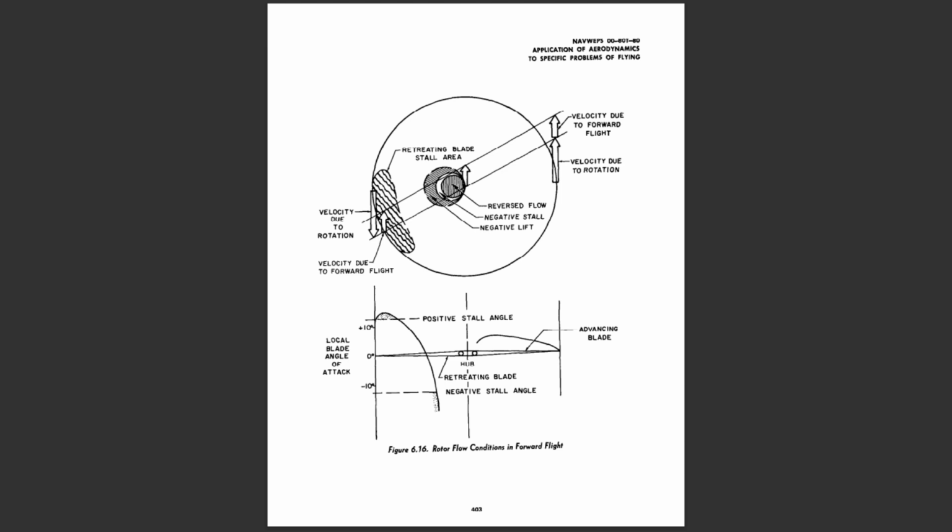If the stall is severe enough to result in pitch-up, forward cyclic to attempt to control pitch-up is ineffective, and may aggravate the stall, since forward cyclic results in an increase in blade angle of attack on the retreating blade. The helicopter will automatically recover from a severe stall, since the airspeed is decreased in the nose-high attitude, but recovery can be assisted by gradual reduction in collective pitch, increasing RPM, and leveling the helicopter with pedal and cyclic stick.